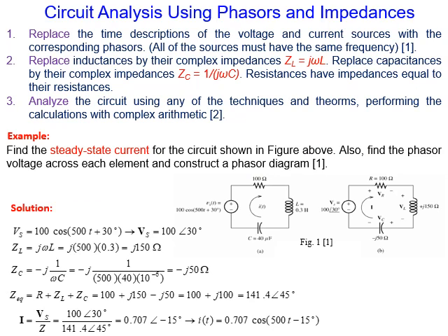Okay. Now, just as a common procedure, when you deal with AC circuits, usually we are given time domain AC circuit parameters, as example, voltage, current. You need to convert from time domain into phasor domain. This is first of all. So all voltages and currents should be in phasor domain, polar representation.